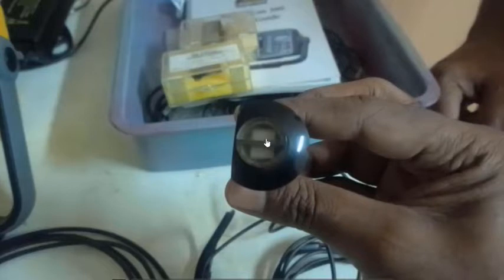These two white crystals over here. That tells you that this is a dual element probe where you have two crystals or two active elements. That is sometimes necessary to get better results. If you have two elements, your reception of the signal may be better.